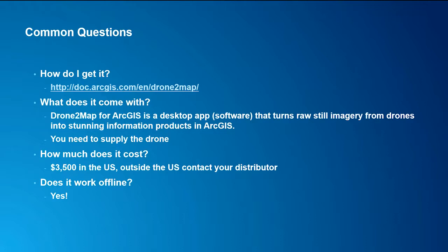Do I need to supply the drone? Yes, you have to supply your own drone. We are drone agnostic. There are some minimum requirements that must be captured on the images in order to make them useful in Drone2Map. There has to be an X, a Y, and a Z value at minimum to be able to pull the products in there. Say I've used the 3DR Solo and really enjoy flying that. I find it easy to fly. But anything that tags the EXIF data onto the imagery is what you need.